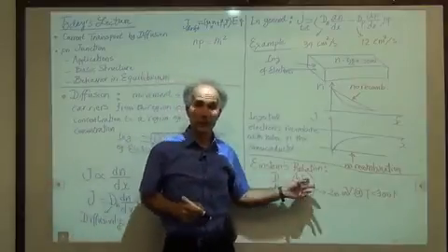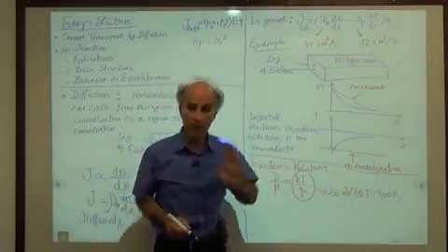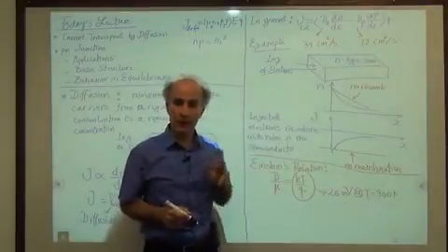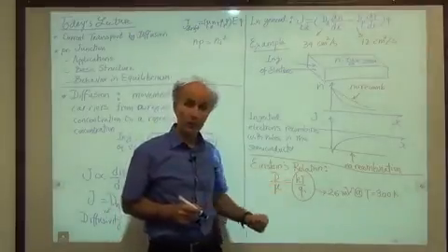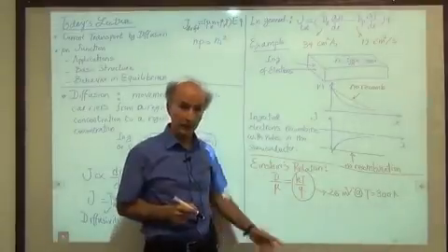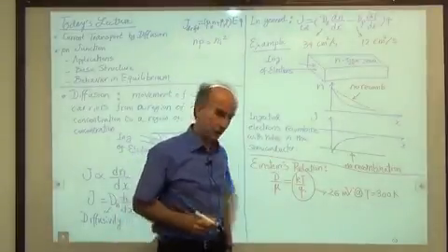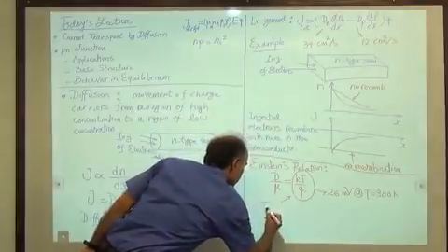As you will see, this quantity kT over Q appears in many, many types of studies that we do in electronics. So it's good to remember this voltage. It's good to remember its value. It's good to remember the expression. Sometimes this is called the thermal voltage. So sometimes we call this the thermal voltage.